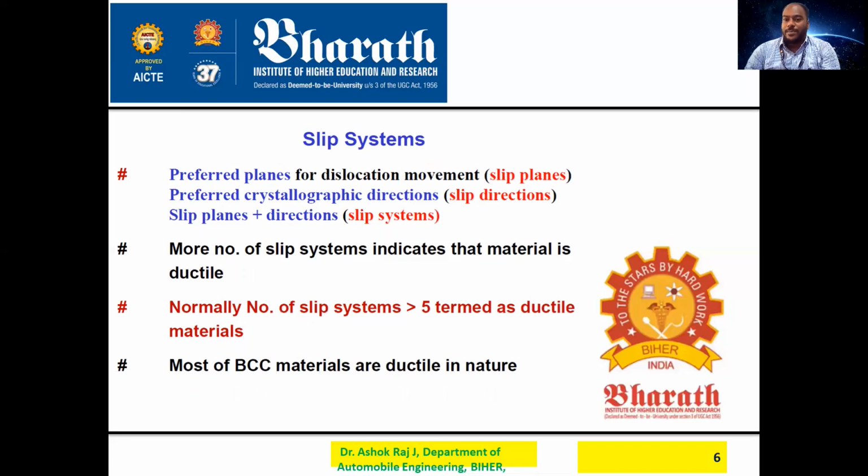So what is a slip system? Preferred planes of the dislocation movement, generally they will call this. You can see the slip planes, and preferred crystallographic directions. So this is our plane. If you are applying the force here, in this direction only, this plane is generally called the slip plane, and this direction is called the slip direction. And slip direction and slip plane, both together they will call the slip system.